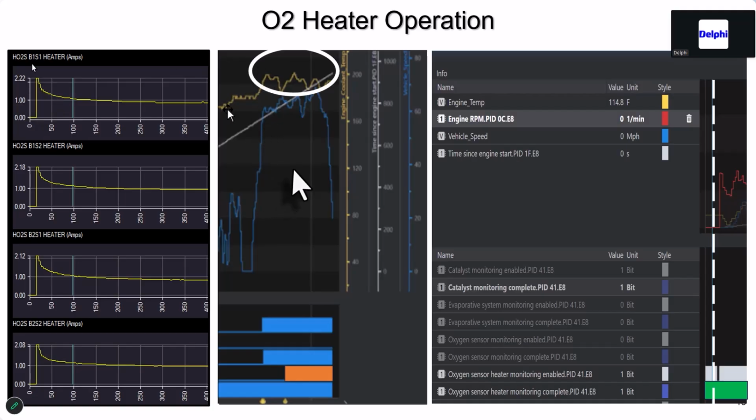This one here was off of Toyota. And if you notice, we're up here at cruise right now. This is a high-speed cruise. And this orange one down here is the O2 heater. So the CAT is run, the O2 is run, and the VVT is run, and the O2 heater is actually running last. So the other thing I want you to get out of your mind is this thing, there's orders to this. This is where patterns can be deceiving. This was the cold engine, the heater ran at cruise.